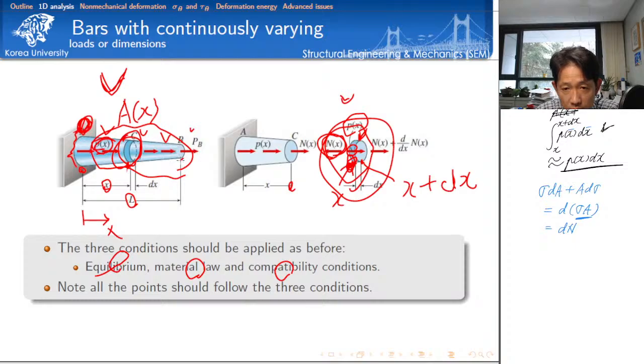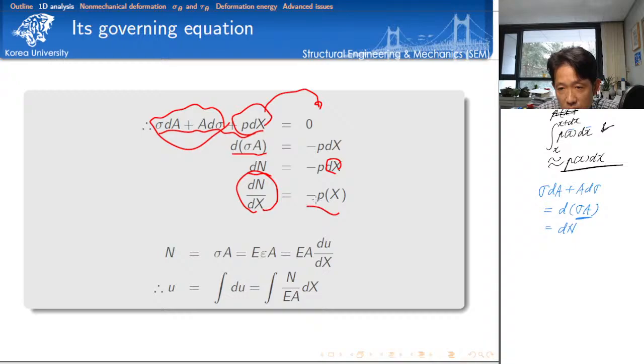And then at the very last point, because there is no external force, the internal force should be equal to 0. Basically, the internal force is decreasing, isn't it? So negative slope. That's why here we have negative slope. So now we can understand our derivation is correct, and we can explain the overall characteristics of this governing equation intuitively.